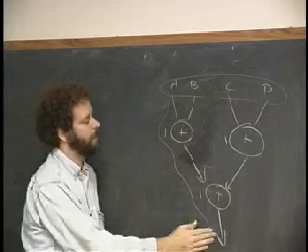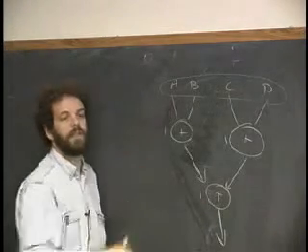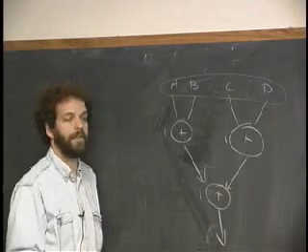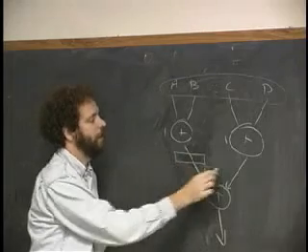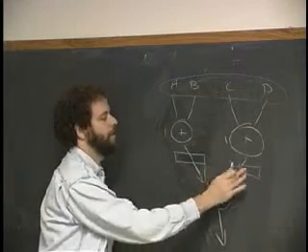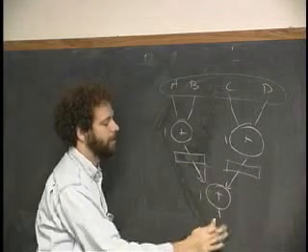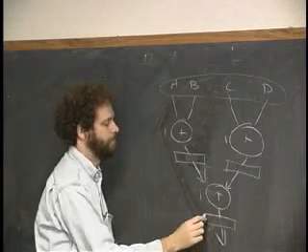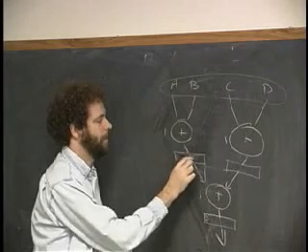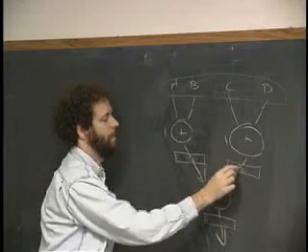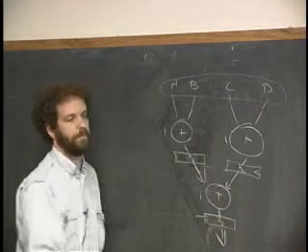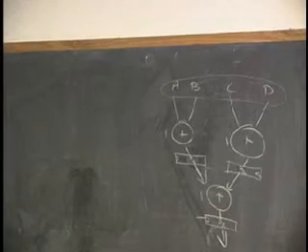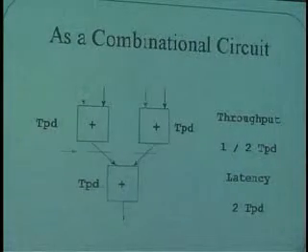So let's stick to the example that's on the slide, which is this one here. How can we make a circuit like this operate more quickly than if we just hooked up the adders just like this? And the answer is that we could put registers in over here, and in general, we put one on the output as well. Like so. Okay? I don't know if that's on the next slide or not.